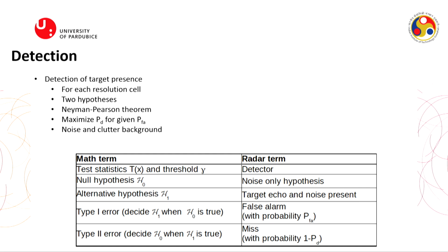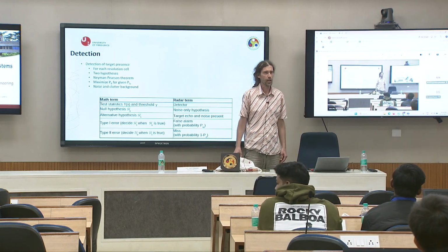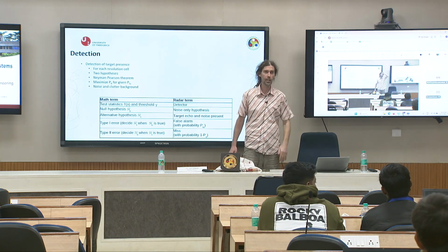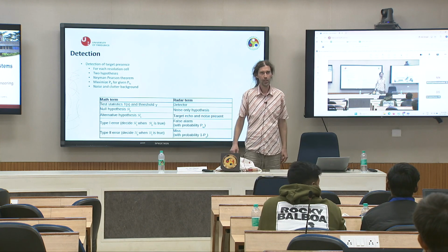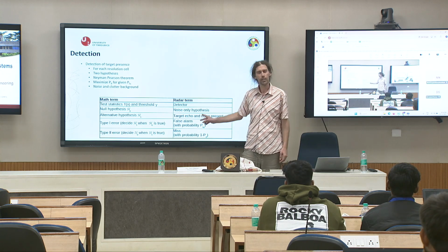And what happens? On your screen you will see so many targets, and it is not true. If I set the opposite, so detection threshold very high, then I can miss a big target. Why? Because I am expecting such a high amplitude, but unfortunately this is a weak target, so low reflection. So we also need statistics, and this is a little like a crystal ball.